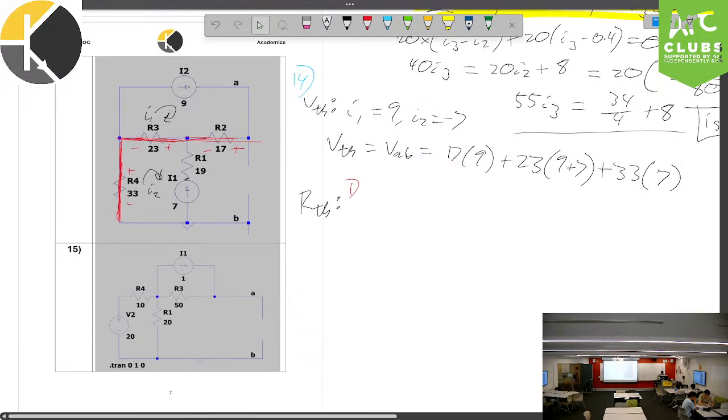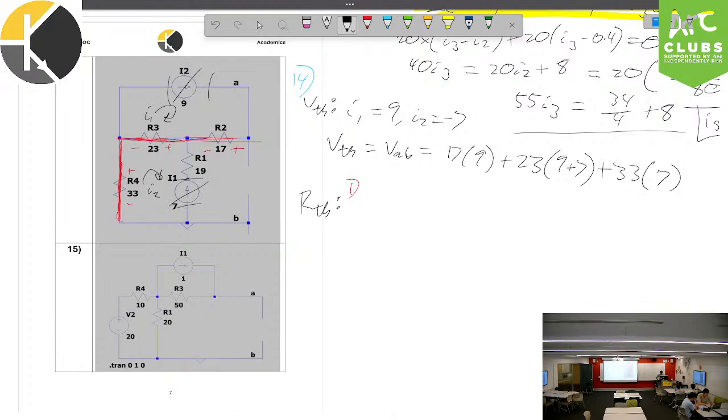Thevenin, method 1, we turn them off. So that's cut off. And now I have this kind of dangling resistor over here. I'm actually just going to rub out everything I've drawn, just so everyone can see it a lot clearer. Because method 1, we only care about the resistors and what happens to the sources. So let's do that.